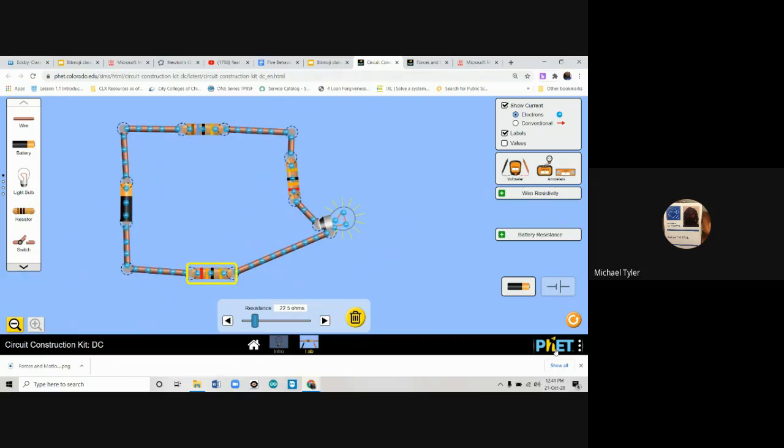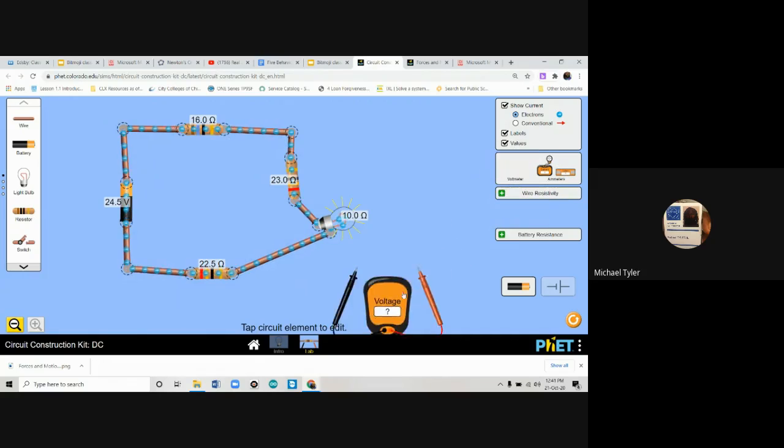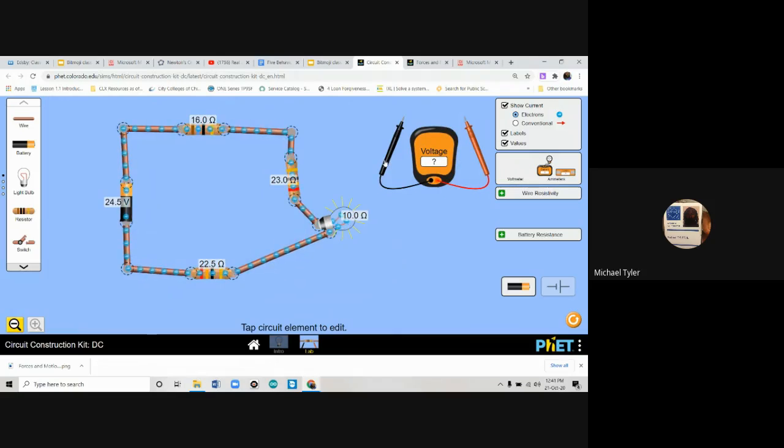You're gonna go over here and take a snapshot, click turn the values back on, make sure they're there too. But before you take your snapshot, I want you to use these tools to get into this problem. So I want you to measure how much is coming off of the bulb. So one black lead goes to the exit of the electrons. The other one is the entry. Okay, can you see what I'm doing? I'm making sure it's connected on 2 points of the bulb. So the black goes to the bottom part of the bulb connection. The red goes to the top part. There's 2 connections for that bulb to start.